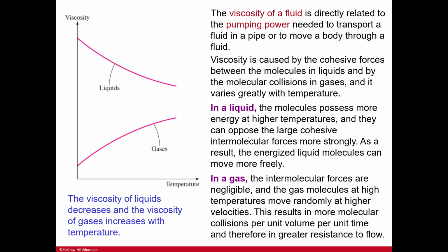Viscosity is caused by the cohesive forces between the molecules, which we need to hold those together in liquids, and by the molecular collisions in gases, and it varies greatly with temperature. Okay? And remember, those cohesive forces between the molecules, we have more of those or stronger amounts of those in liquids versus gases, and that's why we're able to keep it all together. In a liquid, the molecules possess more energy at higher temperatures, and they can oppose the large cohesive intermolecular forces more strongly. As a result, the energized liquid molecules can move more freely.